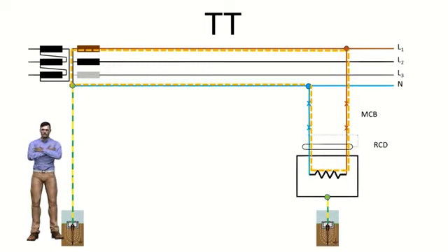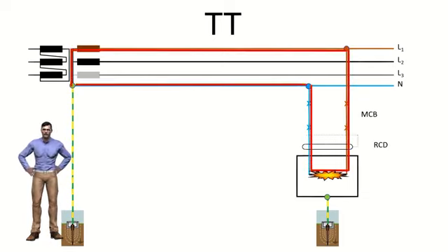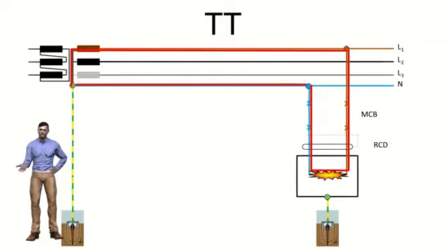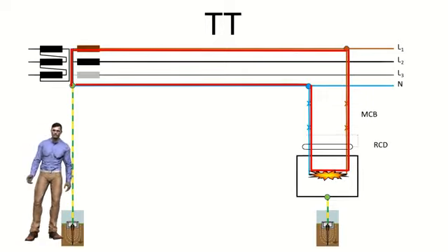Under normal conditions with the protection switches closed, a current lower than the nominal of the installation will flow and the earth leakage currents will be relatively small. In the event of a fault between two phases, the loop that is formed will basically consist of the active cables and the transformer coil, so its impedance will be very small, and in this case a high current will be generated.